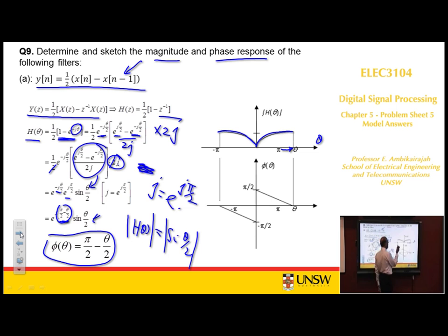Now remember, at that position, magnitude is 0. So in the phase, at that position, there should be a pi jump. So you basically go and start to put a value there. Substitute at theta equals 0, you get pi over 2. Okay, you put pi over 2 there, and you must have a pi jump, definitely, before you draw the negative part.